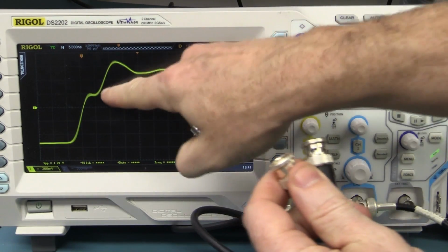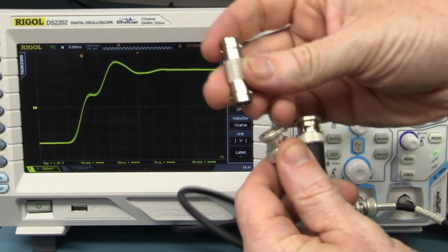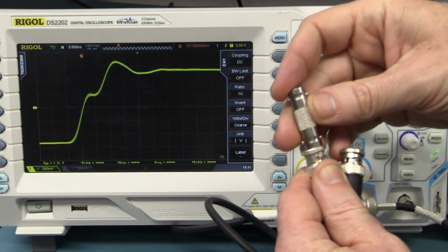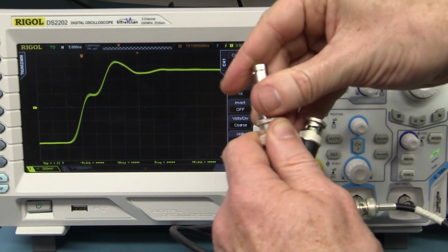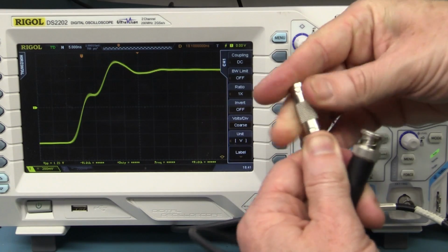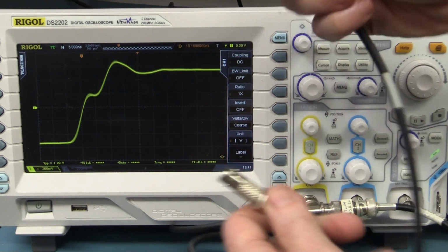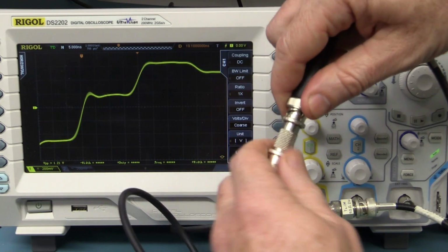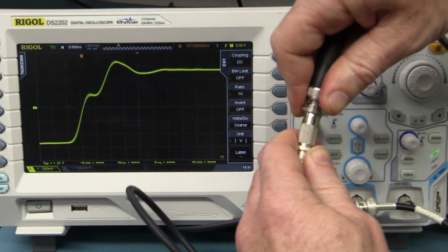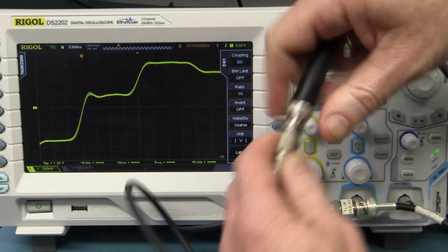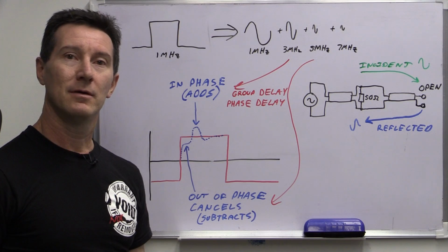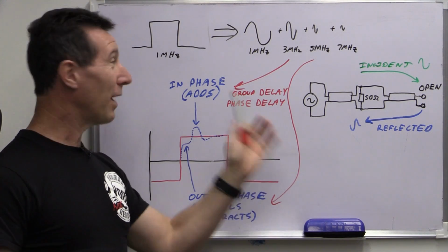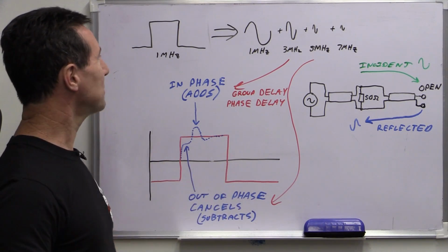And you'll notice that change even if I just add a little tiny barrel adapter like that to it. Look at that, you see? It moves back just a tiny smidgen. So if we add another coax, which is exactly the same length, about 2 feet or whatever, look at that. Bam! Everything changes because of the length of our stub here. And I'll just give you a very quick whiteboard explanation of what's happening here.